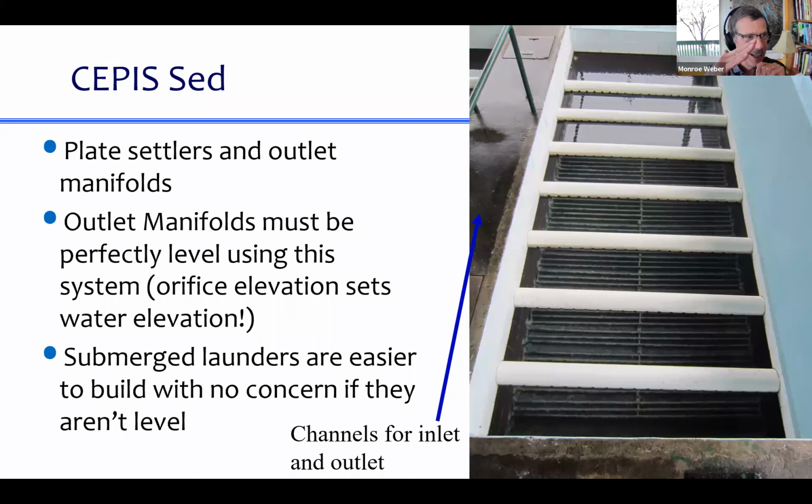You see that? If that pipe isn't level but it's sloped, then the orifices that are down further will be the ones that will get all the water. Right? There's holes all along here. The lower level orifices will have a higher head pushing water in, so they'll get all the water, and you won't get uniform flow.